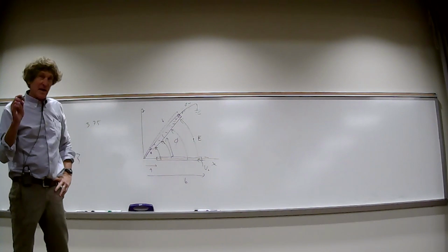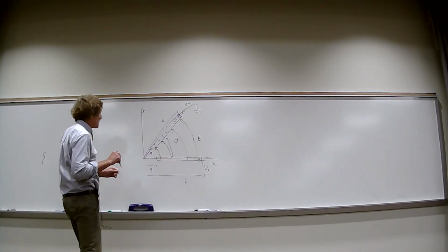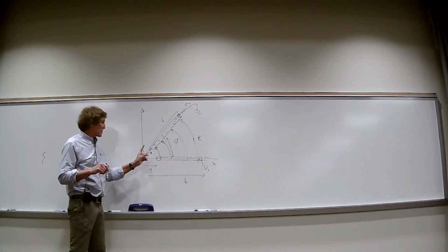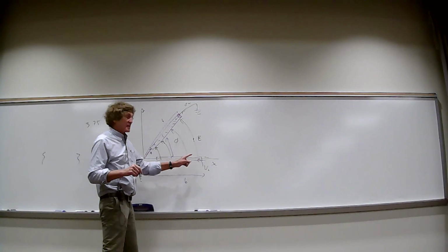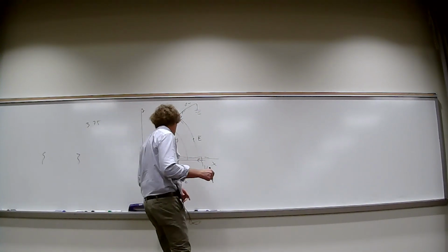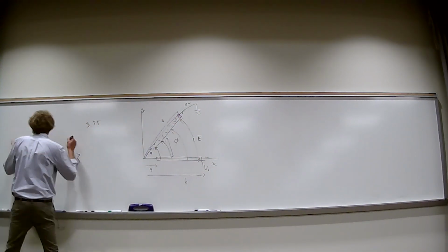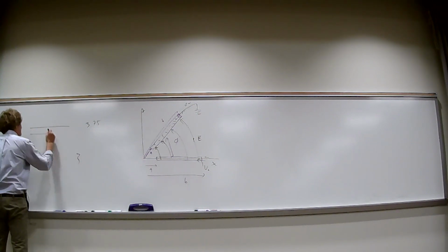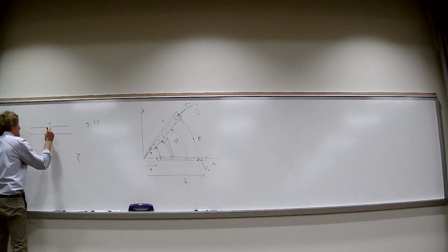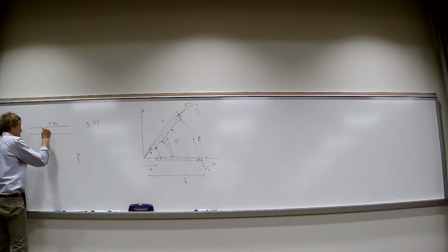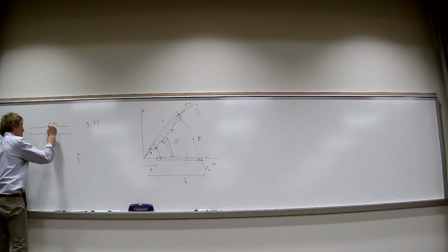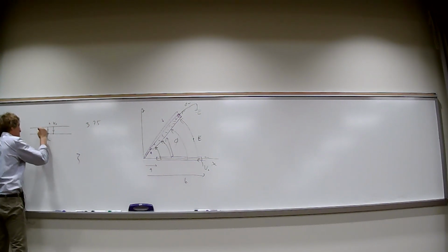Now there's something else. Is there anything in the book about neglecting or ignoring fringing fields? Yes. All right, here's what a fringing field is in essence. If you had a planar capacitor like this, just a planar capacitor, and you put a voltage, say V naught, on this, and you grounded this, I'm trying to make it as simple as possible. In the center, you can see the electric field would be straight down.